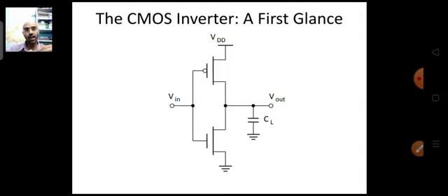Whenever you have, let's say, a transistor and some resistance connected to it, and you want to determine the quiescent point, the operating point of this transistor, that at any applied voltage, where will be the quiescent point of this circuit, or where will be the stable point, or at which point it will be biased. That biasing voltage will be determined by the load line analysis.